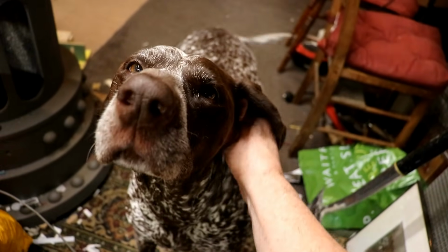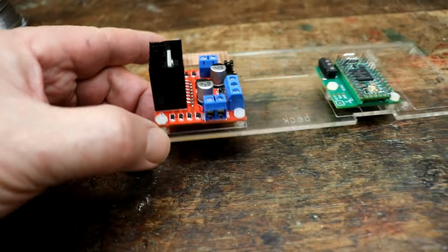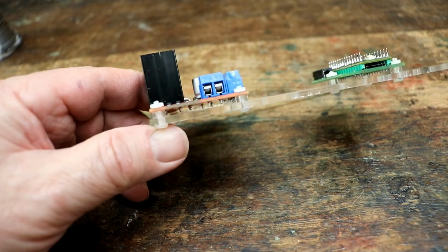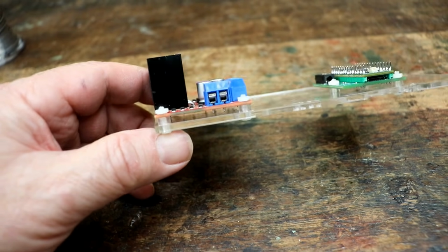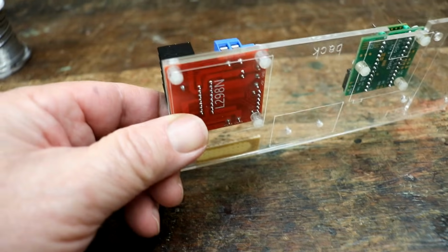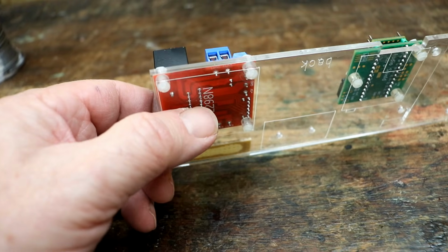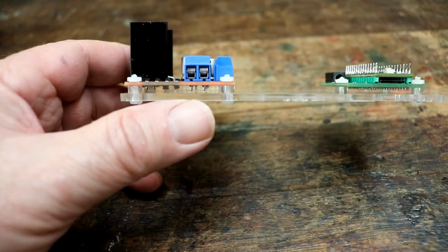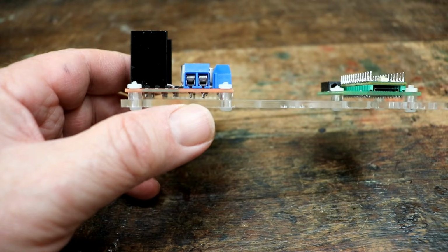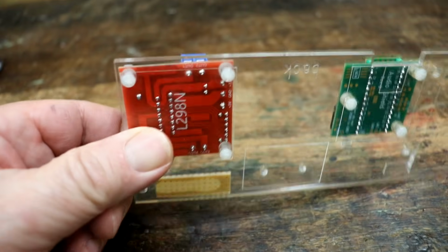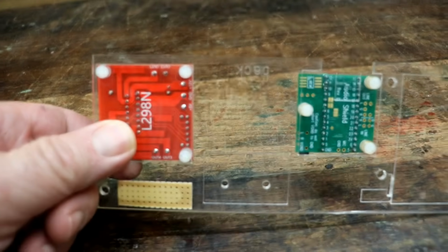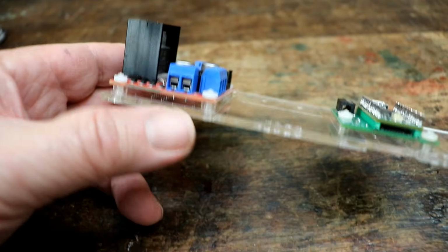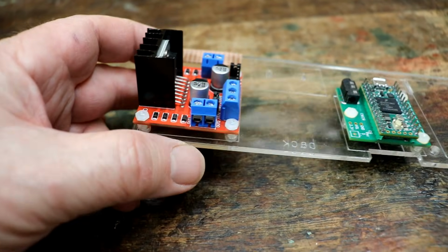I've got them screwed down with plastic screws, nylon ones. You could use wood screws or anything else as long as they're small enough to fit through the holes. Just be aware, of course, that you have all these solder blobs underneath and bits of wire sticking out, so you need spacers. I wouldn't recommend using metal washers because sometimes the tracks are very close to the fixing holes and they could actually short circuit bits and pieces. Some sort of insulating spacer would be great.